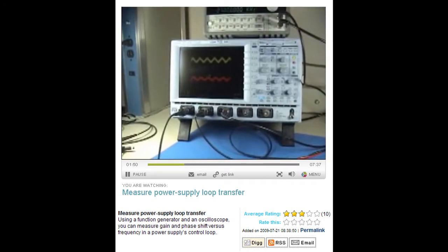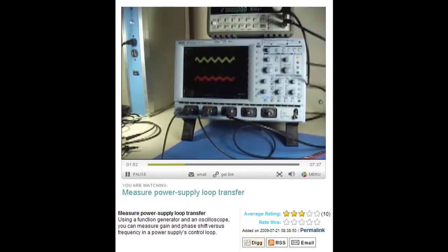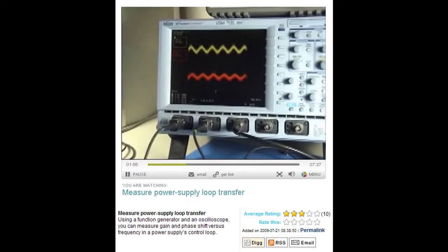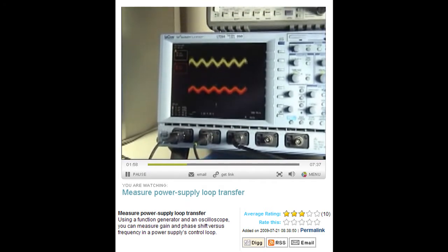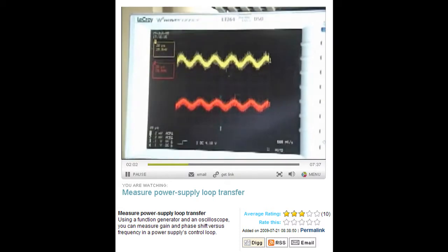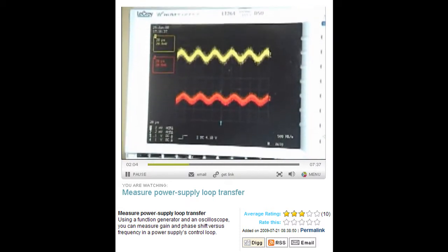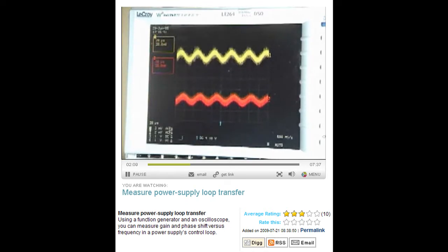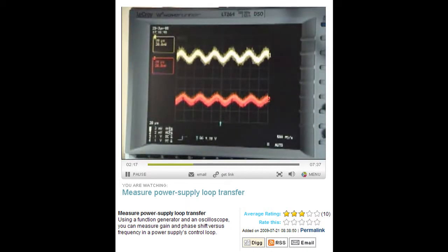And now, when looking at the two waveforms that I measure, we can see the voltage measurement on the top, channel 1, of one side of the injected signal, and as channel 2 on the bottom you see the waveform of the other side of the 20 ohm resistor where I injected the signal.